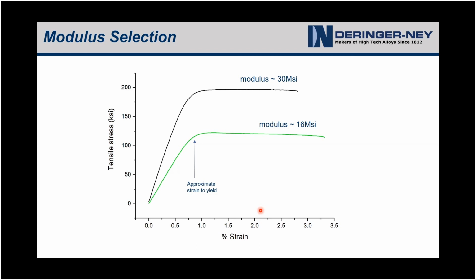and first start out with what kind of range of modulus, especially because there's a lot of material options that are available in the range of modulus between 16 MSI and 30 MSI. Oh, sorry, I've got it later in GPa. It's like 110 GPa to like 220 GPa.